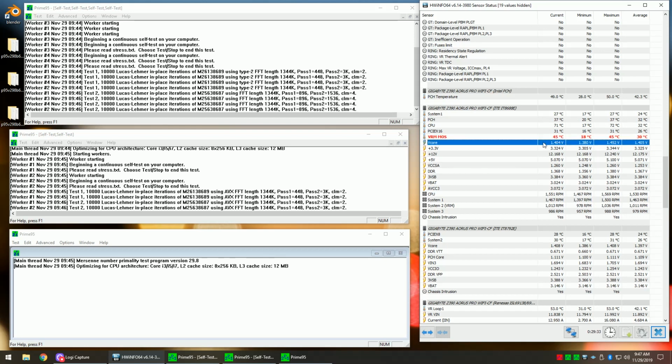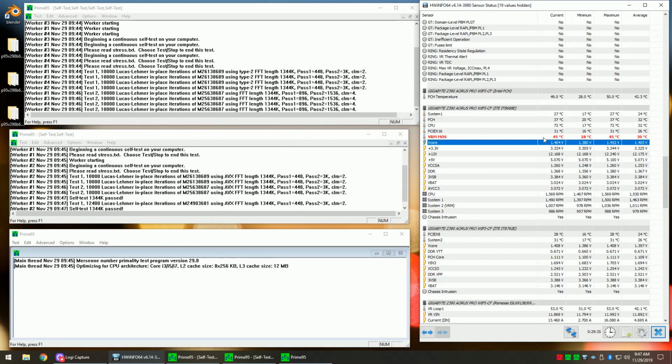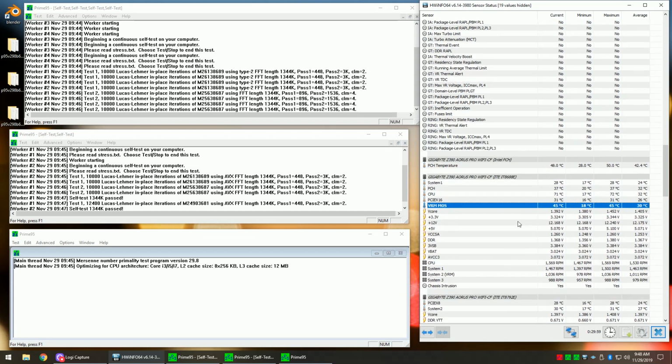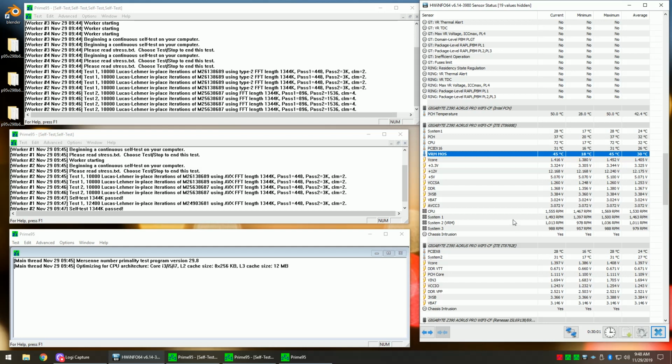But if, for example, you had, say, a Z370 and you were running this 9700K on that, you would likely be running in the 80s and likely getting closer, especially if I was running all of the primes, including the last one. You'd likely see the temperatures go even higher, and with those higher temperatures, you'd probably be seeing the Z370 hit 90s and therefore start thermal throttling the processor due to the VRM not being able to handle the juice. But since we're on a Z390, that was kind of designed to match the 9700K, 9900K with the higher voltage pull, and therefore has a better VRM on it, and therefore keeps the temperatures cooler.